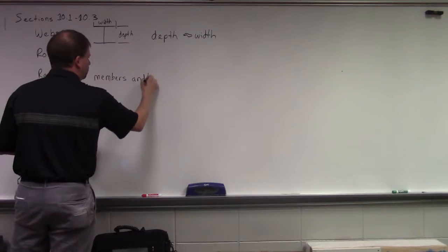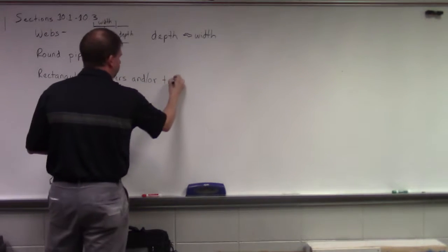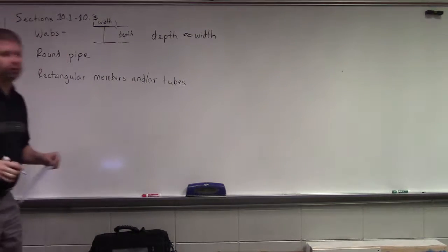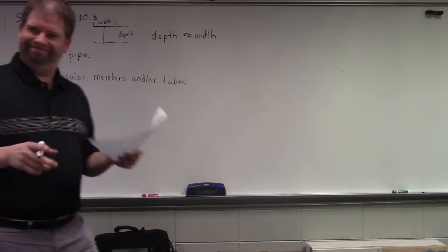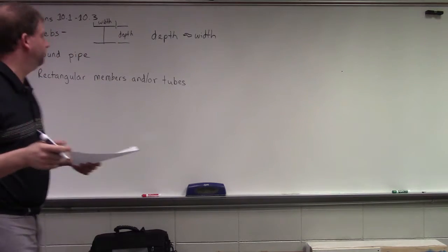And then rectangular members and or tubes. Okay, so those would be the big things that we'll think about when we're talking about structural steel. So the major force that you want to resist with your structural steel, what is it going to be? Shear. Bending. Compression. Inertia. Compression, right?